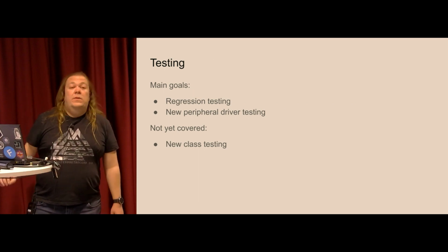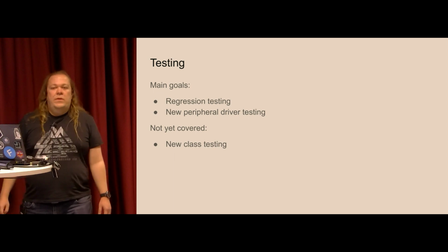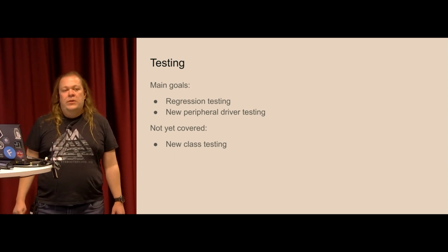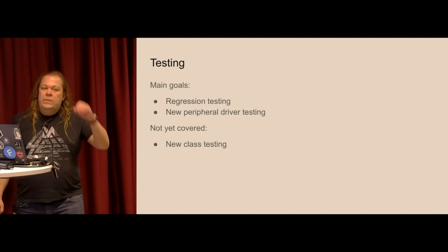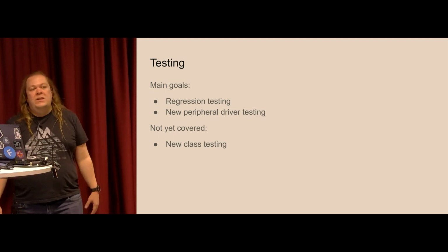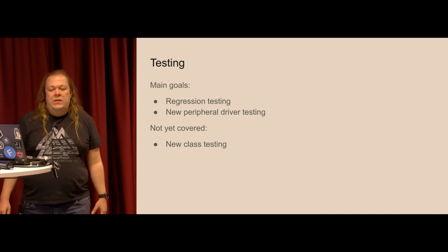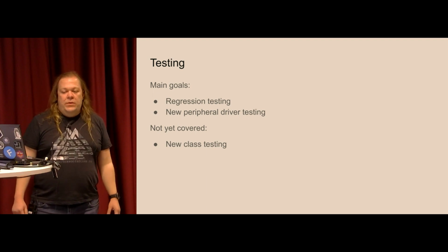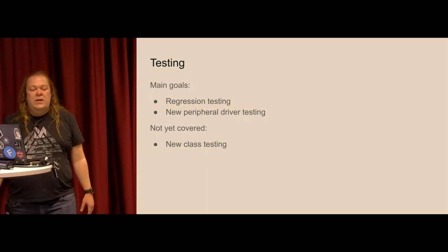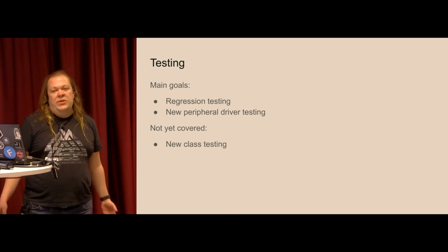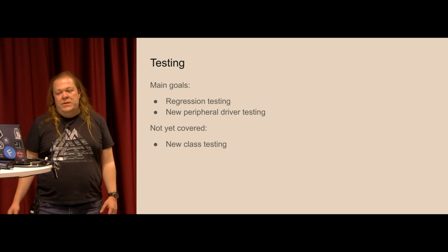What about testing? For example, you implemented something already. It kind of works, but you are still not sure that it works fully. Or, for example, you have a driver and someone makes some modifications to it, and you want to make sure that it still works correctly in all of the cases. So regression testing is the number one goal here, especially if there is a driver that supports multiple microcontrollers. If you add support for just one new one, you still have to test all the others.